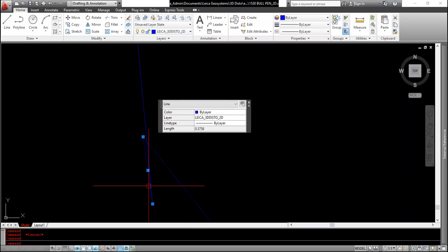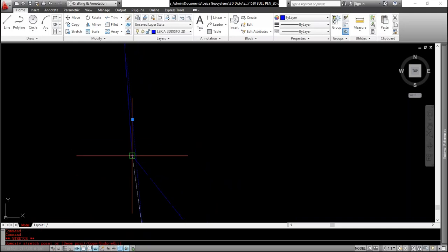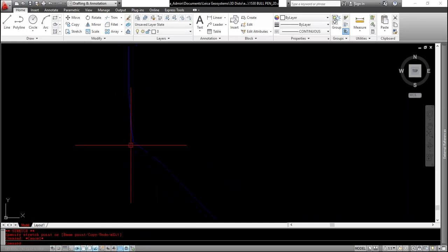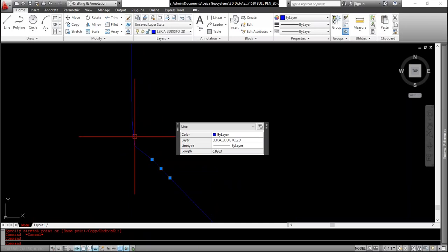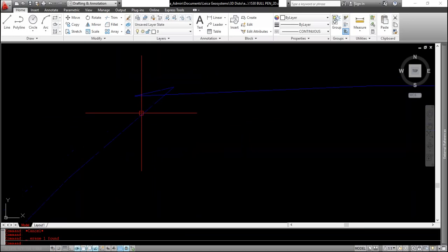So I know that there's a couple points here that I might have mistaken. Like this should go here and this should go here, kind of a thing. And if that doesn't look quite right, you can also do a chamfer and connect those. Every time I do this, I always double check to see what the size is. So right now we're just a little over 1/16 of an inch there. And if I were to delete this line, it gives us a better corner. So I would go through this whole thing and make sure that those are all looking okay.